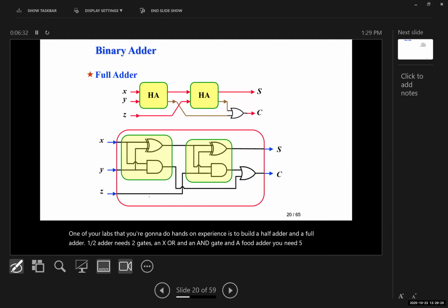And in one of your labs, you're going to build an adder subtractor. You're going to give it 2 random numbers like 2 plus 3. You have to convert that obviously first to binary. And there's another combinational logic circuit that converts decimal to binary, and I'll show you how that works as well. You feed it through a binary adder, and you can add them or subtract them. This is actually the basics of any calculator that you have. It works exactly on this principle. You can easily use them as an adder, subtractor, multiplier. Again, a multiplier is basically some adders combined together.